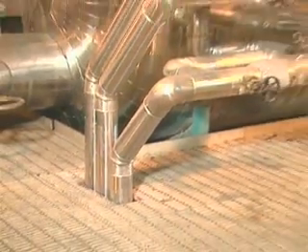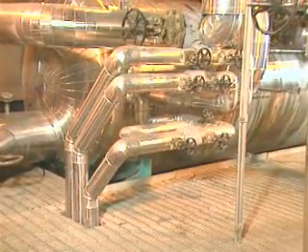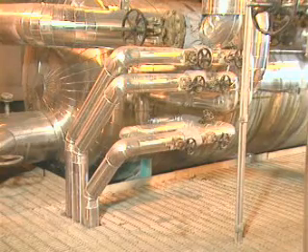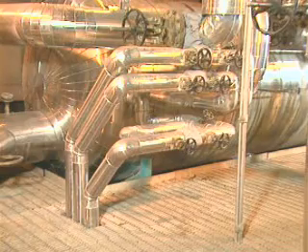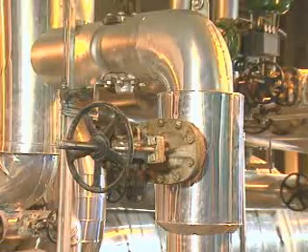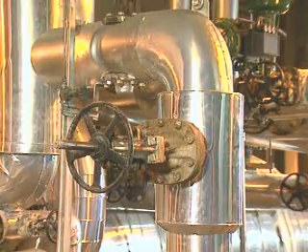Both deaerators and hot surge tanks often have additional connections. Examples are connections from the higher pressure feed water heater's cascading drain system and connections to the vent system from the high pressure heaters.